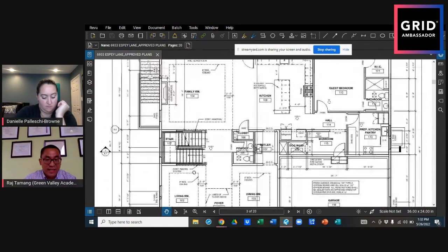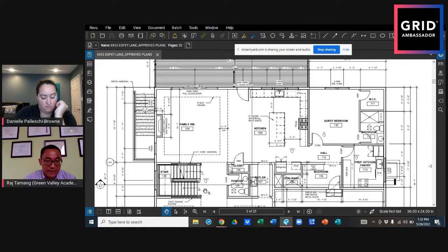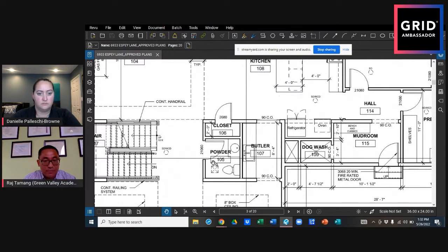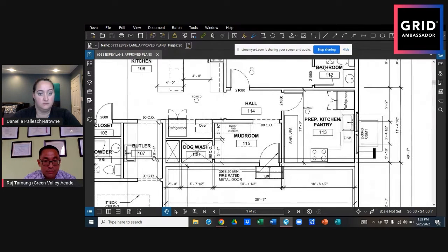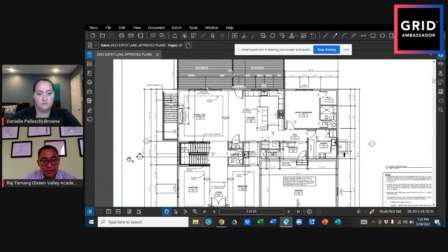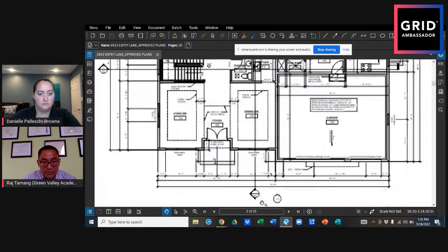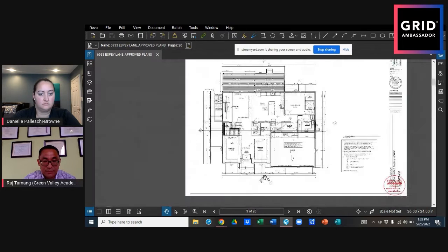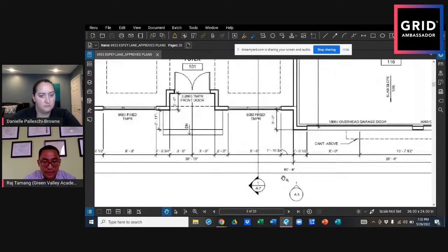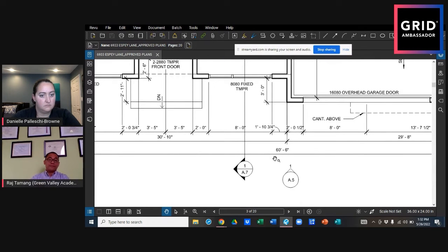So whatever I cut, because when I cut a section right here, I'm cutting right through the stairs, and on the backside I still see some of the doors, right? We show that. I'm cutting right through the powder room and the door. All of this one, you have to cut it. So that's the direction. Cut the section looking up. And the other direction is here. You cut right through it, and you're looking right to left.